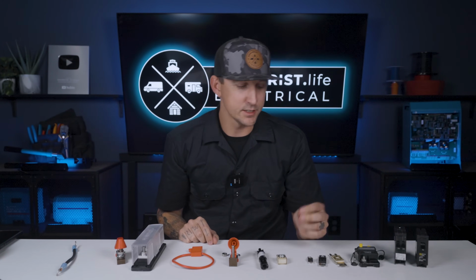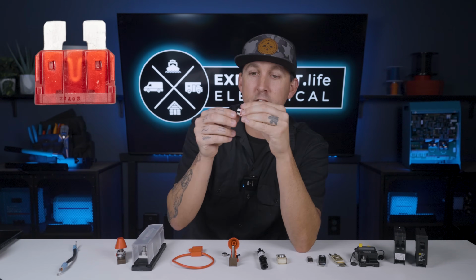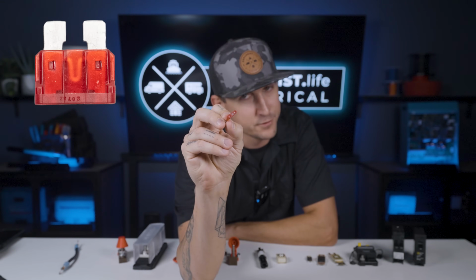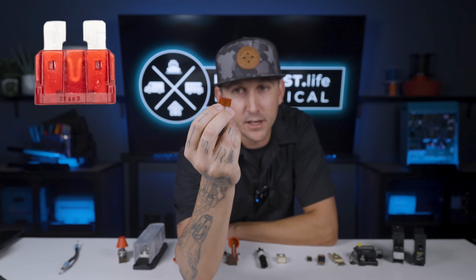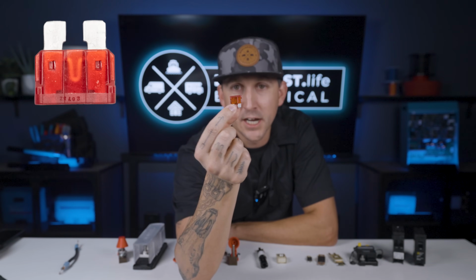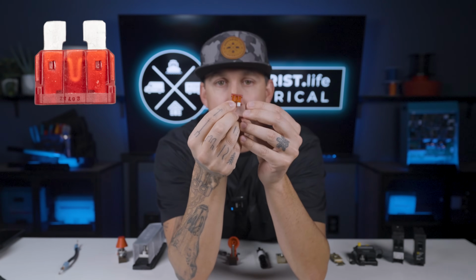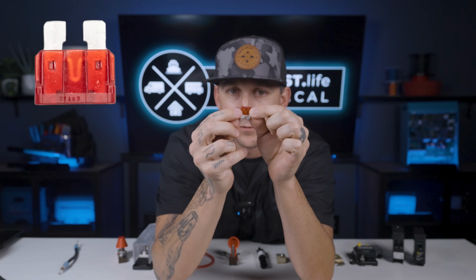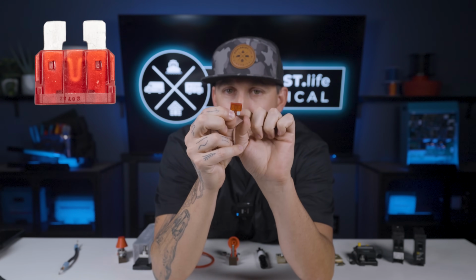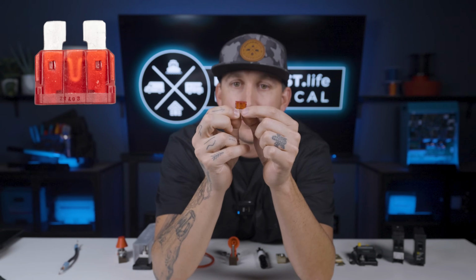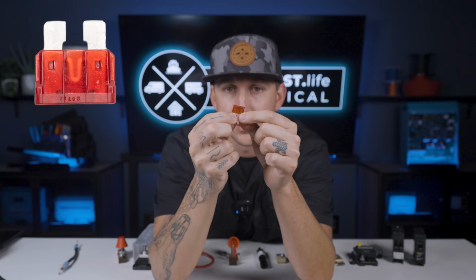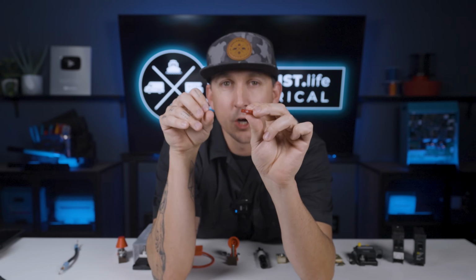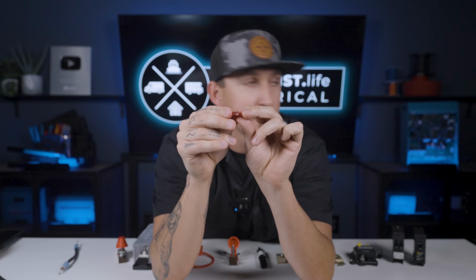The next fuse that we're going to talk about is the blade fuse, and this is a very typical blade fuse. Any car is pretty much going to have these up underneath the dash. I think anybody with a car has probably used or changed these, and they work in similar fashion to all the other fuses we've talked about. Power goes in, power comes out, and there's a little filament on the inside that will melt and stop the flow of power if the circuit is overloaded or there's a short circuit. It comes in all kinds of different ratings. Generally, let's call it 1 amp to, I think, 30 amps is the biggest that we carry.